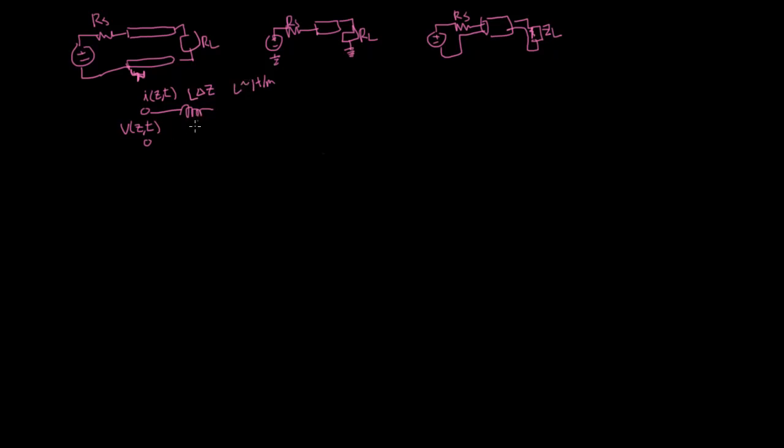What this basically is saying is that you have an inductor that's in series, which means that if you change the current instantaneously, the current in the transmission line is going to have a little bit of a lag. And then separately, the same thing also happens to the voltage. So you end up having a shunt capacitor.